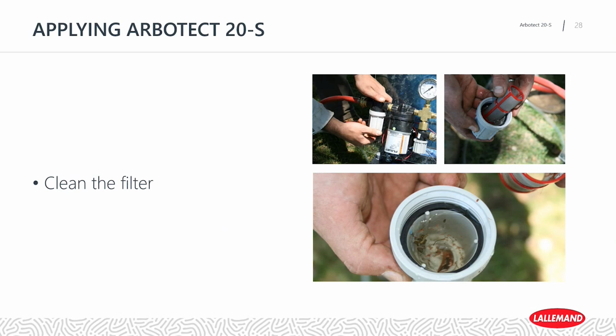Before each use, we want to make sure that we're checking and or cleaning the pump filter. A clogged filter will result in a slower uptake. And when we're doing this, it's important to be careful to not misplace the O-ring. Once that O-ring is lost, air can get into the pump, which will hinder the infusion process.